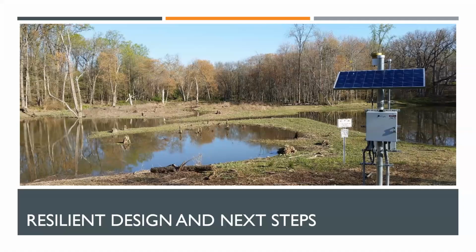So to answer your question, what RAND has done, their downscaling study does a really nice job for events that range from the 1-year storm or the 2-year storm all the way up to the 100-year storm event, projecting those. They do that for different emissions scenarios, so RCP 4.5 and 8.5. One of the challenges with downscaling is it's really difficult to get to the temporal resolution that you need for really localized stormwater modeling, so some of your H&H, hydrologic and hydraulic modeling.